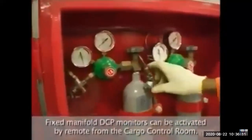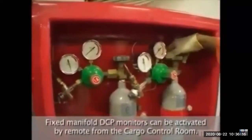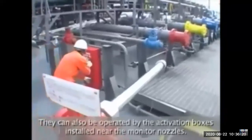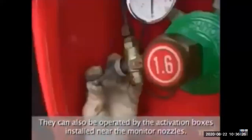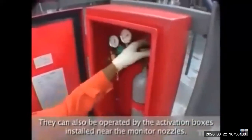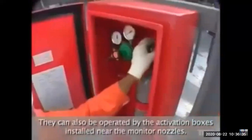If you open from here, the fixed DCP will be activated on both. You have to open both the valves after taking out the pin. In the same way, you have the bottles on the manifold also. Similar system to the CO2 system, and nozzles are activated.